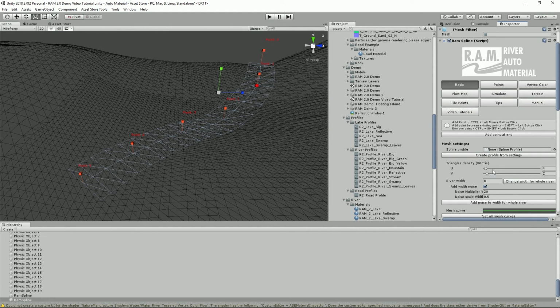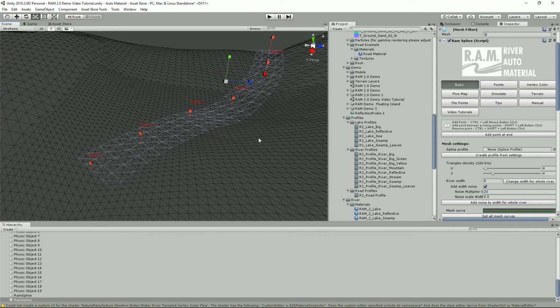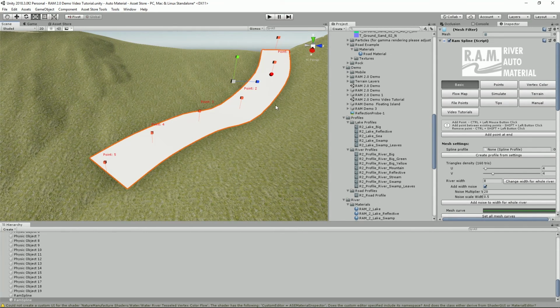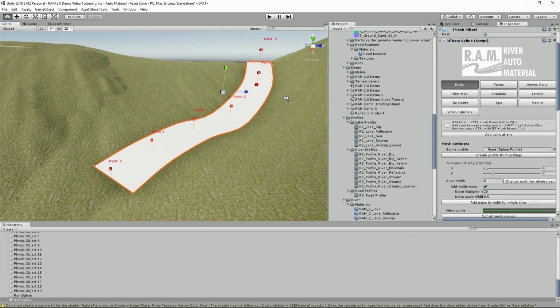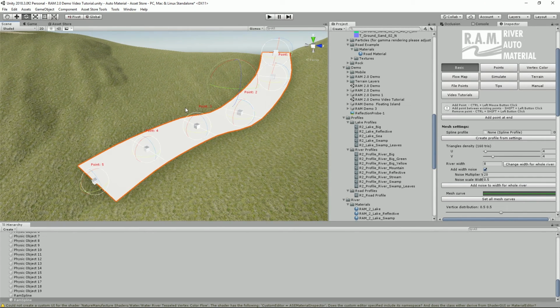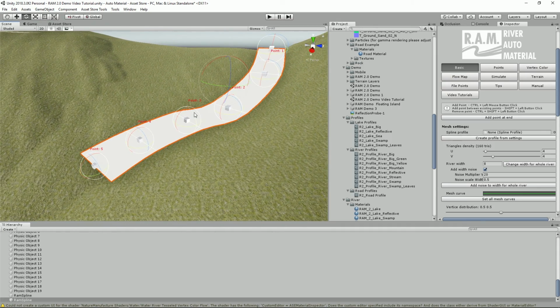If we use the U or V slider, it will change the amount of verts per our spline. We rather advise to use square verts, so equal verts, so tessellation will have no problems, and all effects like vertex color and flowmap will be pretty regular over the shape. We could also change rotation of our spline. We could rotate it as we want. If we change the red angle, it will change vertex normals of the spline, useful for rivers mostly.